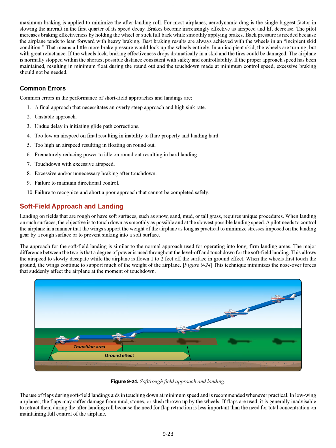7. Touchdown with excessive airspeed. 8. Excessive or unnecessary braking after touchdown. 9. Failure to maintain directional control. 10. Failure to recognize and abort a poor approach that cannot be completed safely.